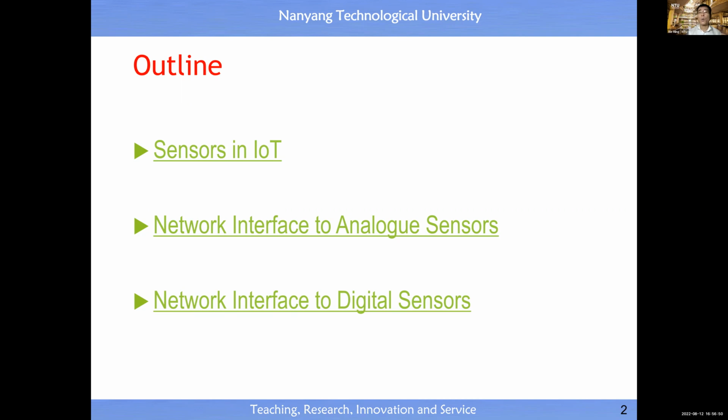As long as we are able to convert the measurement of any physical quantity into voltage, then we can use a microcontroller to do the conversion from analog value into digital number, all right? So now I guess you should believe that by default, a microcontroller is a digital sensor for voltage, all right?